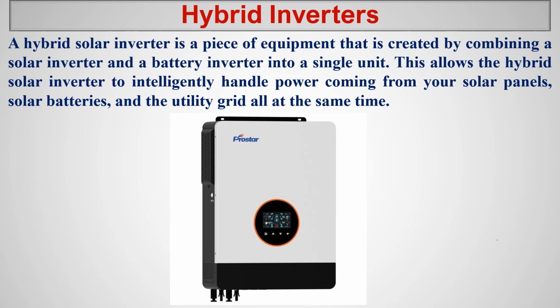So what is the question here? Why do we need a hybrid inverter? Let's say you are going to charge the battery using grid power. Again you can ask the question, why do we want to charge the battery using grid power? Because in developed countries, in off-peak hours you can consume power from the grid at a cheaper price.